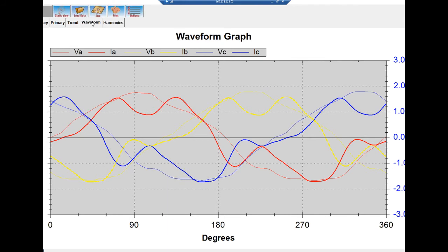So what I can do, if I'm concerned about this harmonic content that I'm seeing at my site, I can save that data and do several things with it. One of them being saving it for later, so I can look at it, take it back to the shop, analyze it, see what might be going on. But the biggest strength that this RW has is to then save this content and regenerate it later. Whether taking the file being generated from the RW and generating it again on the RW, whether it's in the shop or out in the field as a phantom load, or taking the same files that the RW generates, bringing that over to our WattNet suite, and then regenerating that on one of our test boards.